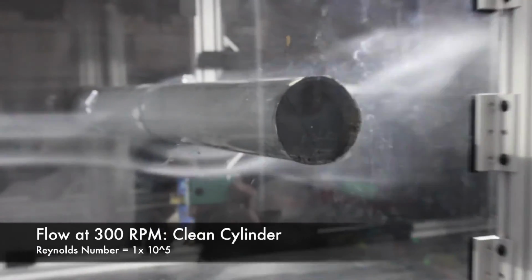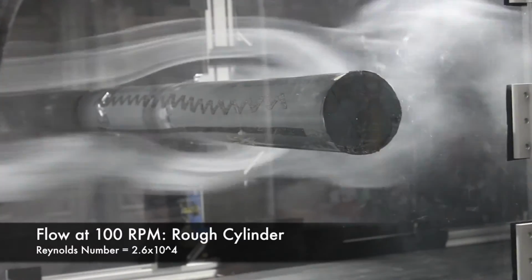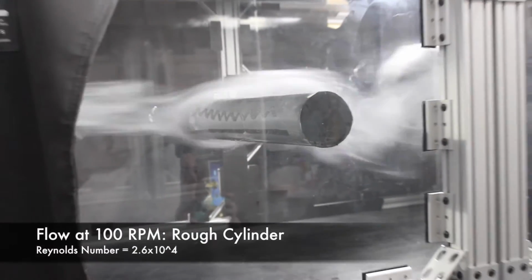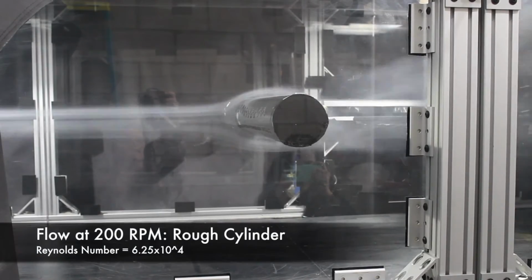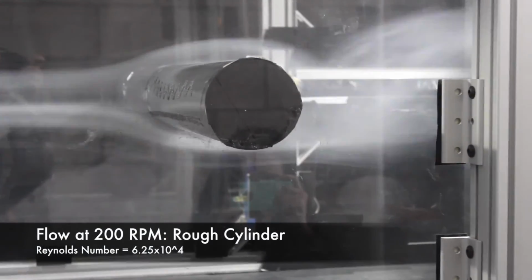Repeat readings and videos were taken as the wind tunnel was stepped back down. Once the wind tunnel was completely shut down, the doors of the test section were opened and trip strips were placed on the cylinder. One trip strip, approximately 1 centimeter thick, cut in a zigzag pattern, was placed approximately 45 degrees above the horizontal on the front face of the cylinder.